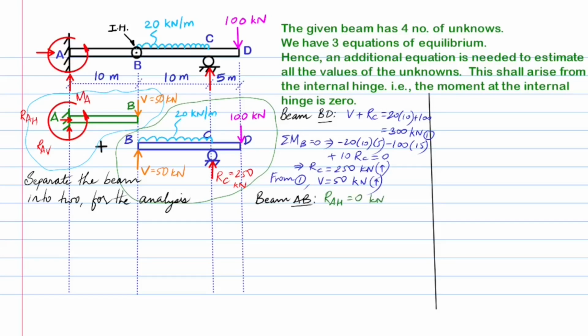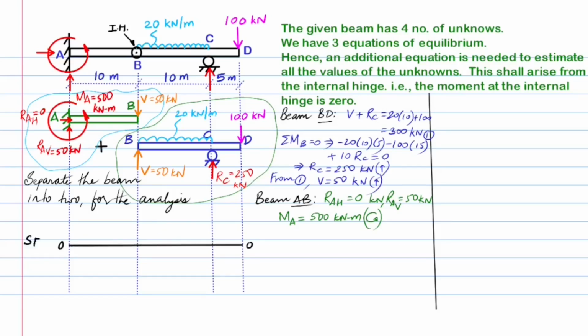Though the reaction forces and moment at A are not required to be found out, if we take reference as A and B for finding shear force and bending moment equations, we still find them and show them on the schematic diagram. We begin writing the equations for shear force and bending moment for the beam BD, for which end B is taken as the reference.